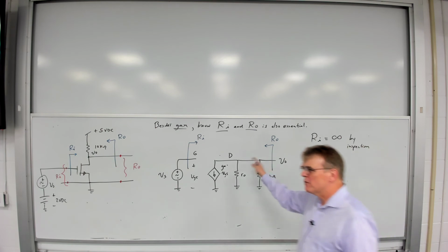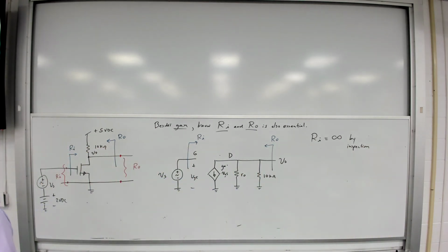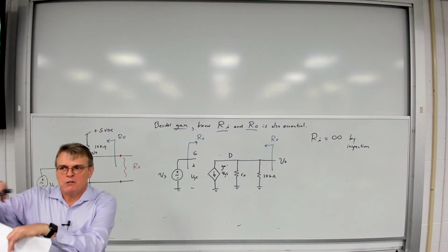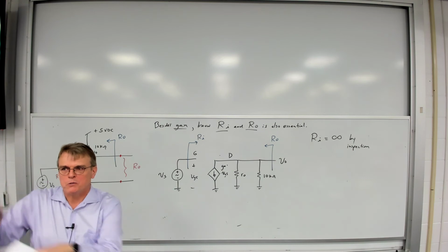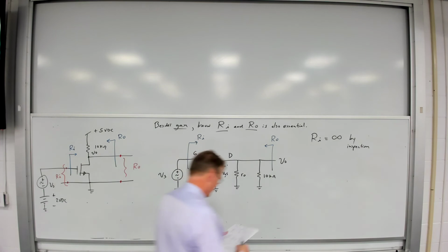What technique do you have to use when you're finding Thevenin resistance in circuits with dependent sources? Source driving technique, right? We're going to zero out all of the independent sources, and then we're going to connect a voltage or current source across the output, and then calculate it using the source driving technique.